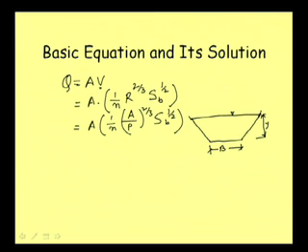And then side slope we specify as z is to 1. That is, for one height, this slope increases, the width increases by z. Okay. So, 1 is to z. Now, what will be the area of this section?